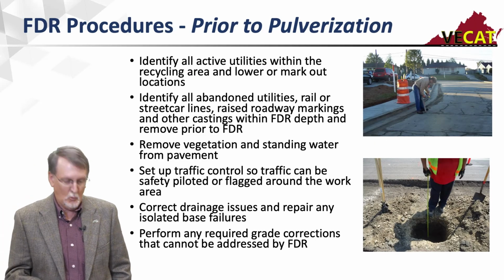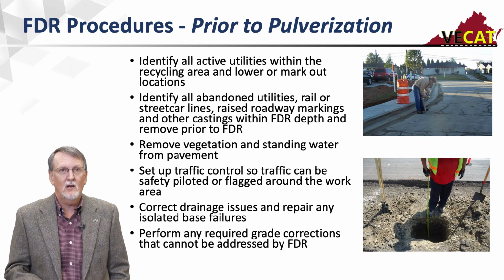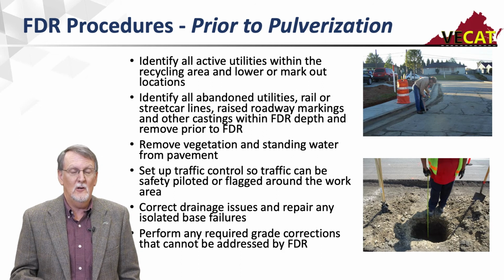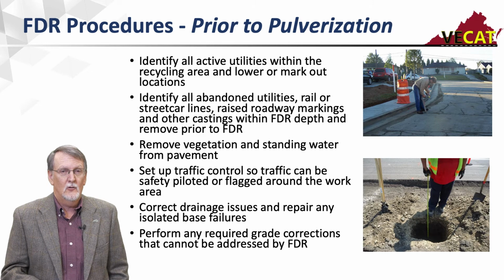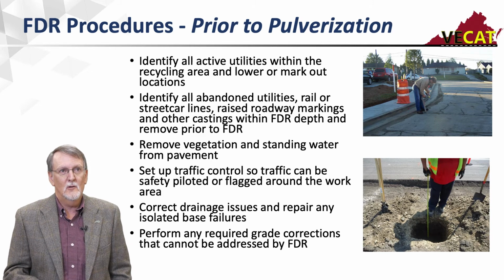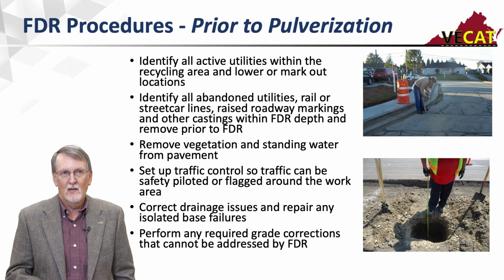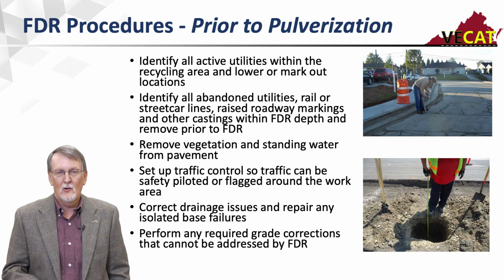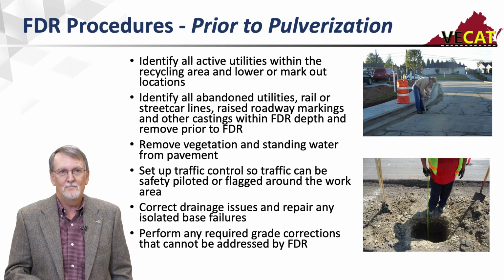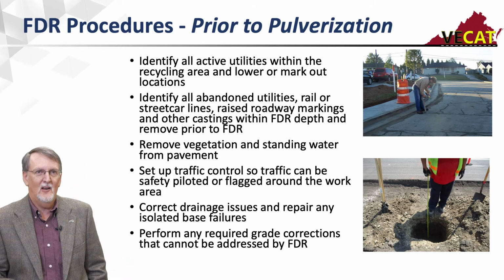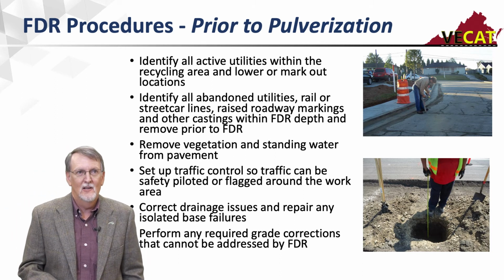Biggest thing is I'm going to be digging into this pavement anywhere from 8 to 12 to 14 inches. So before I start this, I want to identify all active utilities within the recycling area. I want to lower them or mark them out so I can work around them. I need to identify all abandoned utilities.